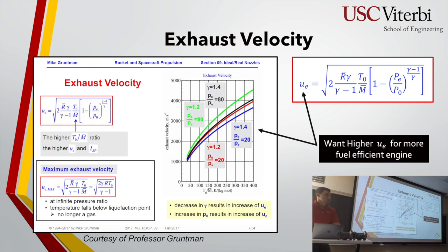Sorry, what's M bar? M bar is your molecular weight of the material of the combustion itself, so your fuel and your propellants. Going back to the costs and benefits, hydrogen, the lowest molecular weight, has the highest Isp. That's also because it has the lowest number here, right? So that right there shows you what that is. And then the higher the temperature, the better, because you have more thermal energy that you can convert into kinetic, right? So that's your chamber temperature?